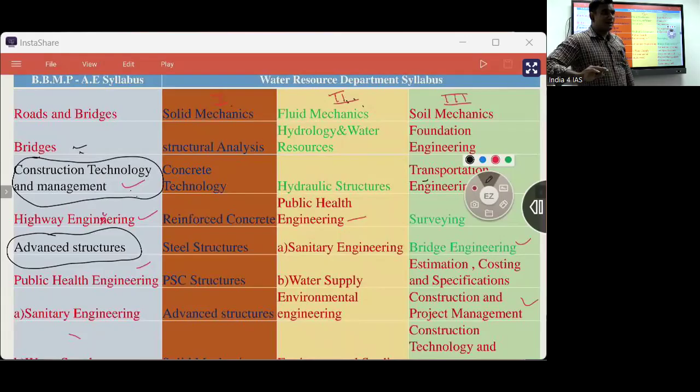No, I'm asking just grade of the cement. That is 33, 43, 53. Grade of the concrete is 5, 10, 15, 20, 25, and so on, 80, 90, all there. That you make sure. So M10, M20, M stands for mix. And that number represents strength for how many days? Very good, 28 days.